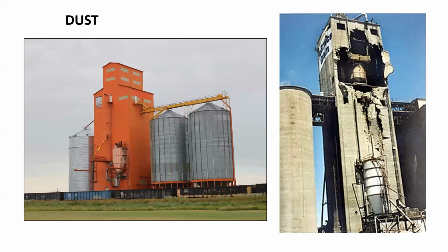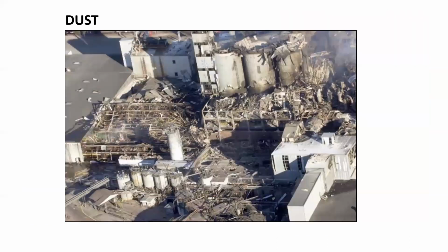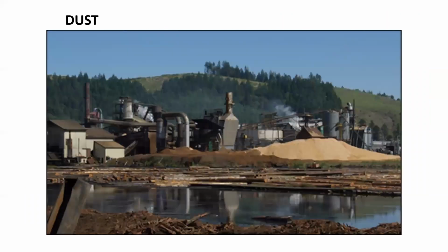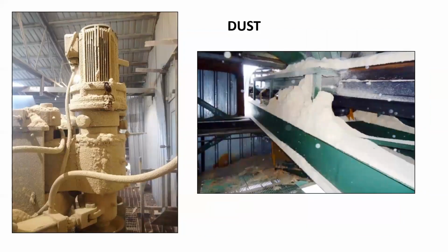Even dusts that we assume are non-hazardous to begin with, if they are blown up into the air and become very small concentrations in clouds of air or dust, they become extremely flammable. Even things such as grain, sugar, and non-dairy coffee whitener. Even sawmills have the possibility of absolute catastrophic damage, as we saw in 2012 in the province of BC.